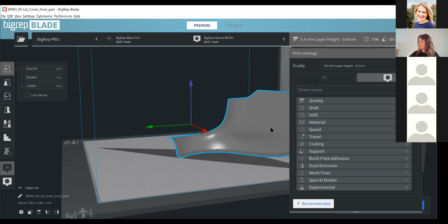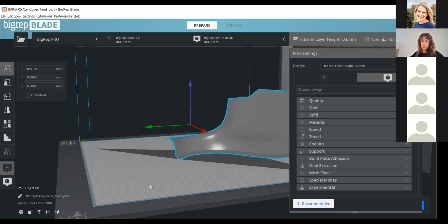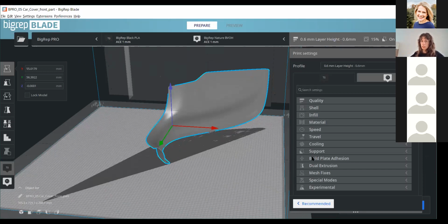As I'm sure some of you that have had experience with 3D printing know, a lot of times printing horizontally is stronger, whereas printing vertically will give you a better surface finish as you'll have that clean buildup of lines. Where you do it horizontal, sometimes you do tend to run into issues of having that topographic look. Obviously, all of that can be adjusted, making the resolution higher, orienting things specifically in a way to sort of avoid that. But for this one, we're going to orient it like so.